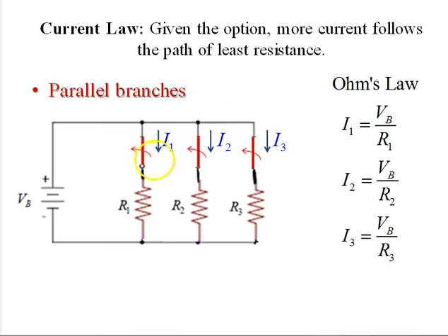When we close all three switches, now we have these three resistors in parallel. They have the same potential difference across them. We know that to be true because they have the same position at the top as at the bottom, because remember, these wires are short circuits. There's no voltage drop across them, so we say they're separated by the same 2 points, so they're all in parallel.